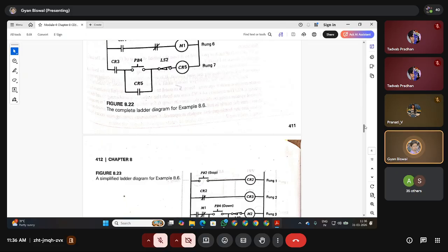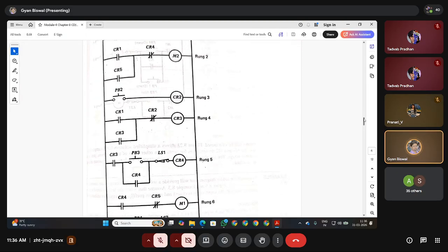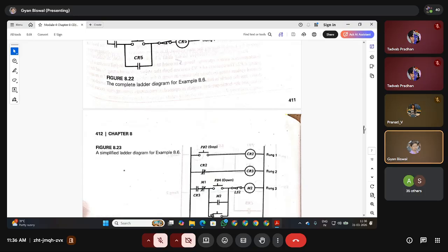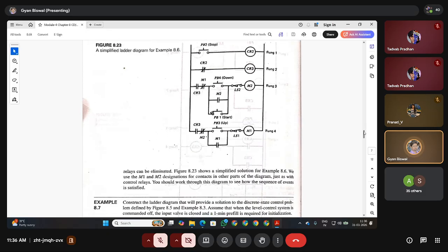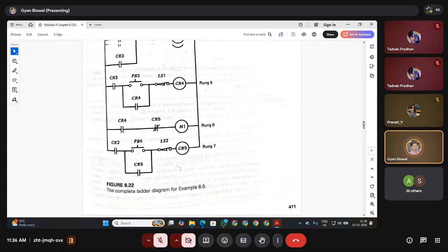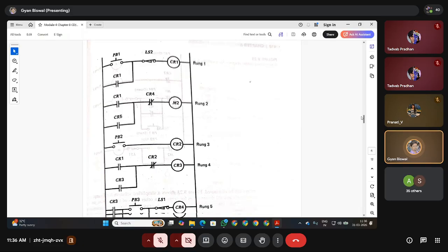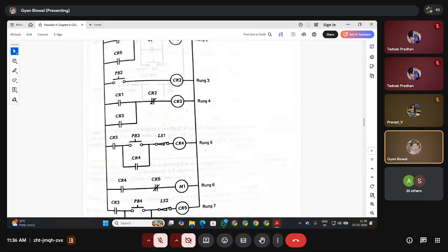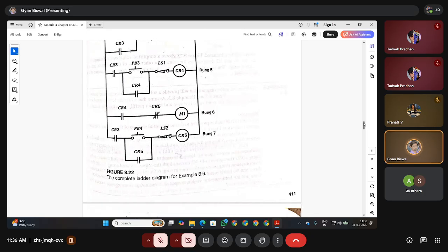So that is the complete physical ladder diagram of this program, the two-stage elevator. Okay. Now, meanwhile, before reaching the optimized, simplified ladder diagram, you see how many physical inputs and outputs are needed here? 4, again 4 here, 8, plus 2, 10, plus 4, 14, isn't it? Here, how many? 5. So 14 plus 5, 19, 3, 22, plus 5, 27. So a minimum of 27 components is needed.